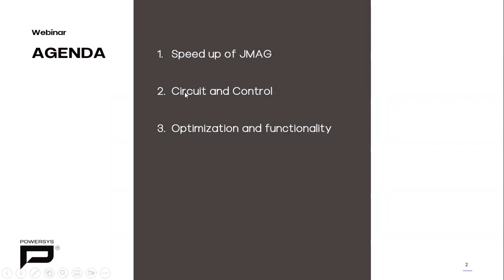And the second thing is that we have seen about the circuit and control. There we have seen that we have introduced different modulation technique macros, and we also saw how to edit the inbuilt macro components without reproducing them. We also saw that to the RT block, different passive components can be added between two terminals.